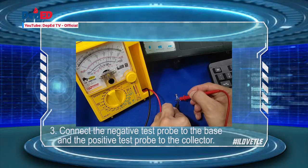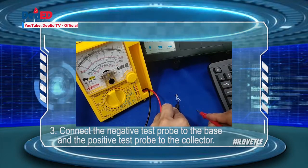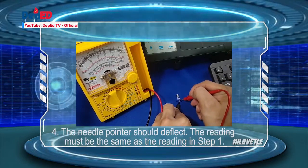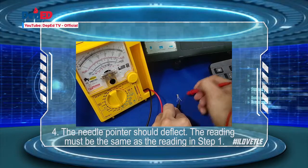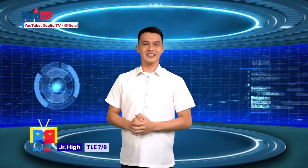Step 3. Connect the negative test probe to the base and the positive test probe to the collector. The needle pointer should deflect. The reading must be the same as the reading in step 1. Perfect! You have learned how to test a transistor.